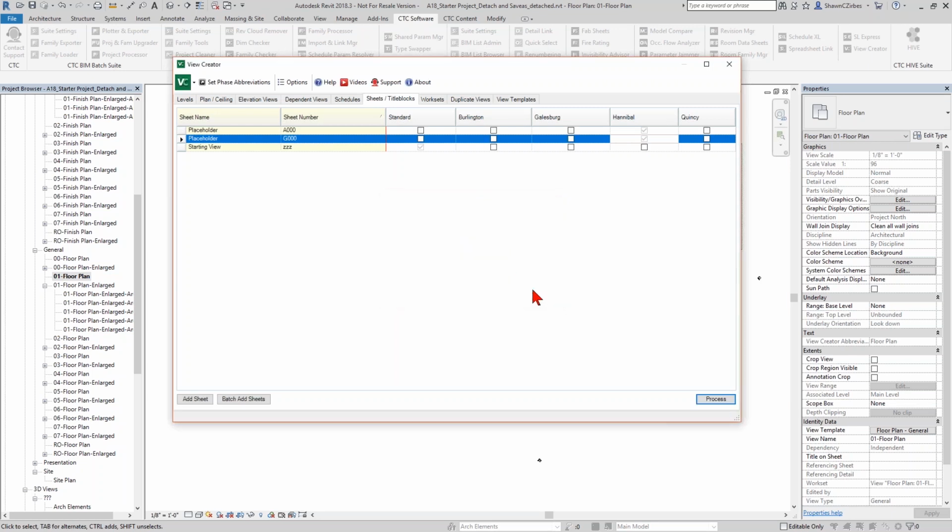I could also use select all instances and swap them that way. But sometimes I need to be a bit more surgical about that, where some sheets show certain things and other sheets show different things. My cover sheet title block is usually different than the main part of my other title blocks. So this gives me the ability to go through and be a bit more surgical, see where things are being applied, and then swap them out.